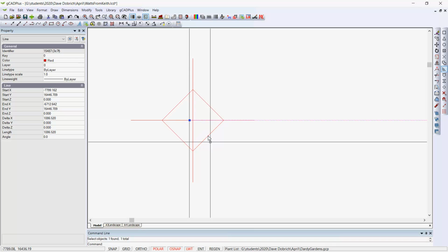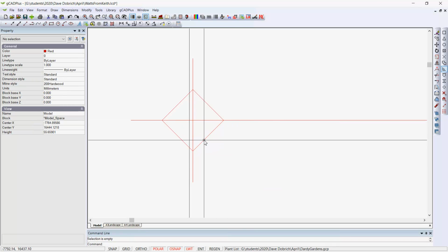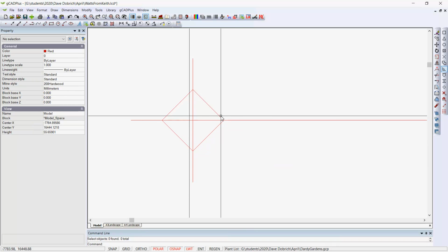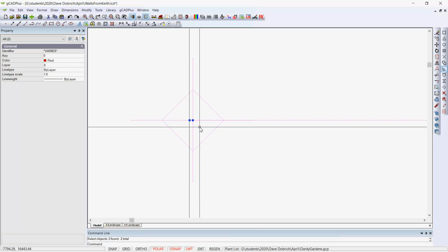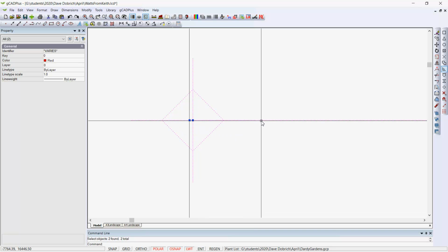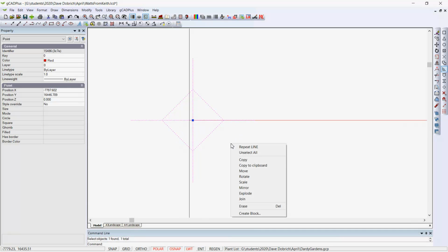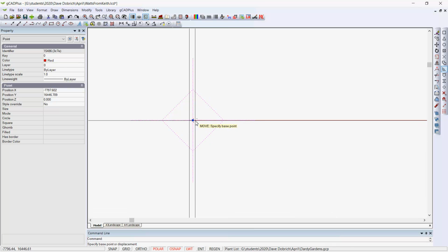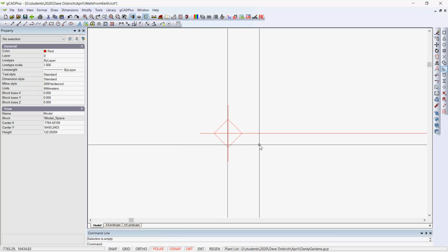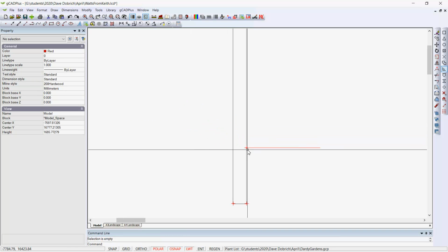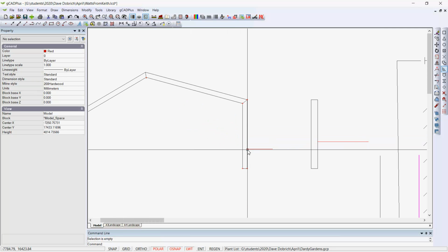We just have to rely on a setting with the eye, and we can pick the point, and we could take this point out, and then we could move that point again by eye. So that's one of the little idiosyncrasies of CAD software. Multi-lines are great, but if you do need to snap two entities within it, there are problems.